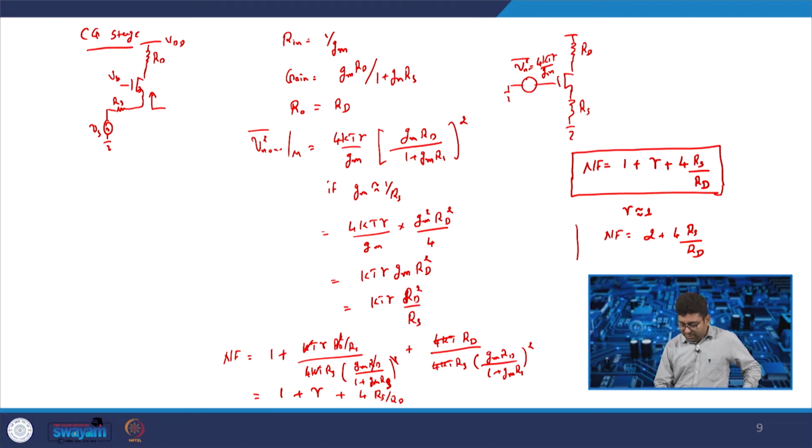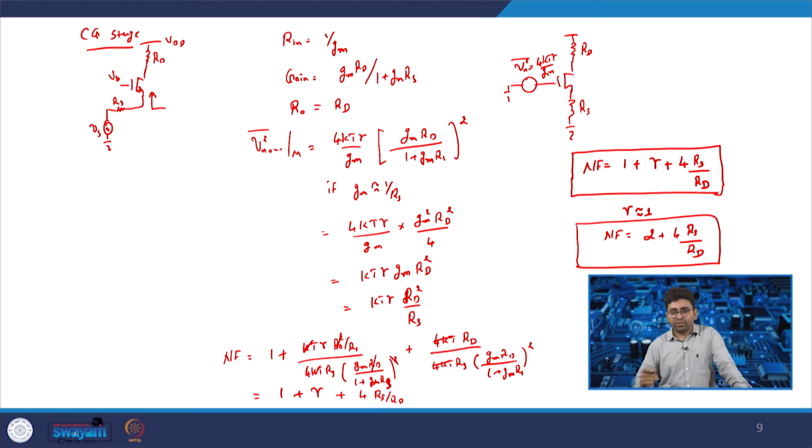So the advantage of this configuration is that all these three configurations, considering the resistive matching, the first, the second resistor feedback in common source, and this common gate configuration, all have a high noise figure. However, they can be used for wideband applications where you do not have a stringent requirement of sensitivity or noise figure, for example IoT, and they also have better impedance matching and are wideband.